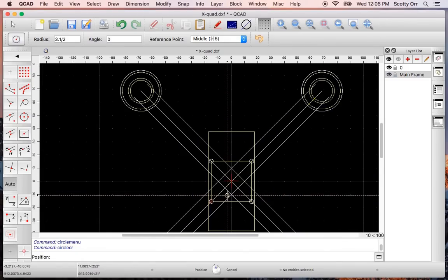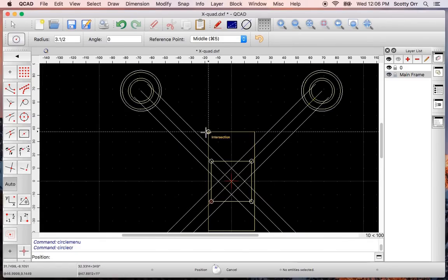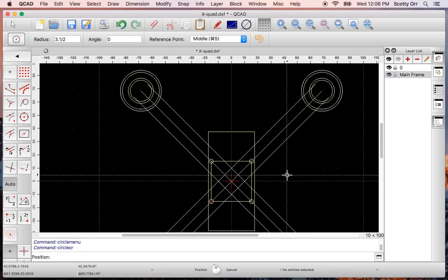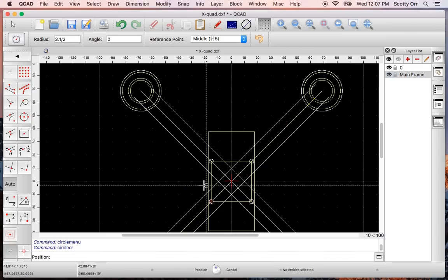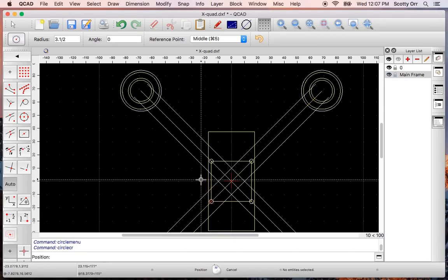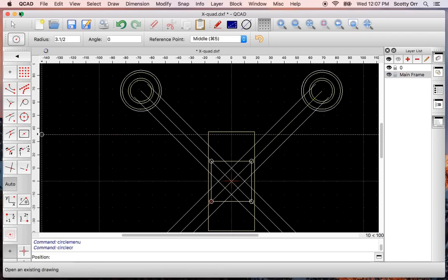The next thing we want to do is we got to consider the battery and the battery strap. We'll assume this is a bottom mount battery, just to keep this simple. And I need a slot for the battery straps that are outside the battery. I like to put them where they are exactly outside the battery. And most battery straps are like 2 centimeters wide, 20 millimeters. So I'm going to make a slot that is 21 millimeters long. Now let me reset this.